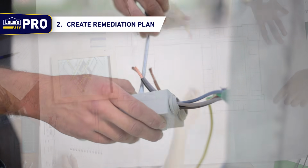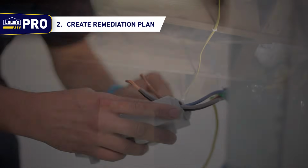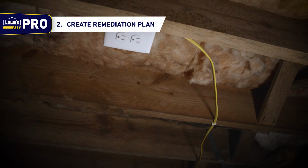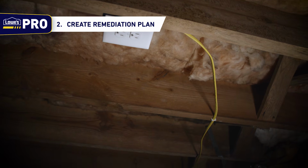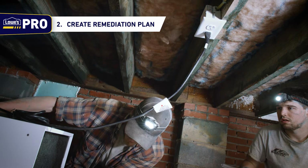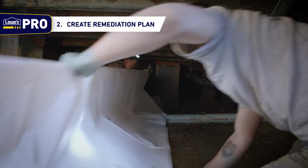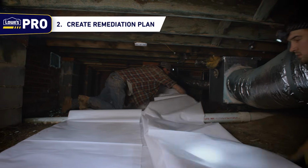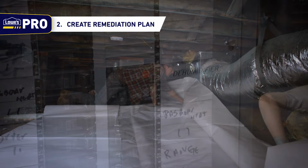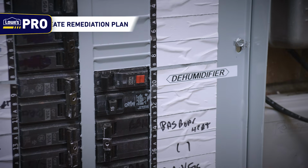throughout the job. Now is also the time to contact an electrician to install a grounded GFCI in the crawlspace to power a dehumidifier if needed. Do this before the remediation to guarantee there is power for work lights and to power any tools needed to complete the remediation. It also lessens the number of people who will need to access the crawlspace after the moisture barrier has been installed, reducing the possibility of the poly being torn. If possible, have the GFCI installed directly to the main panel.